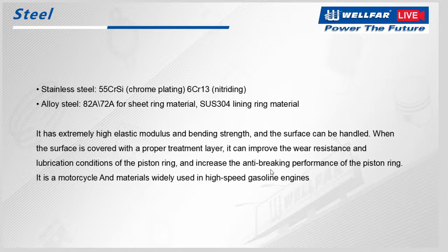It has extremely high elastic and bending strength, and the surface can be treated. When the surface is covered with proper treatment layers, it can improve the wear resistance and lubrication conditions of the piston ring, and increase the anti-breaking performance of the piston ring. It is a material widely used in motorcycle and high-speed gasoline engines.